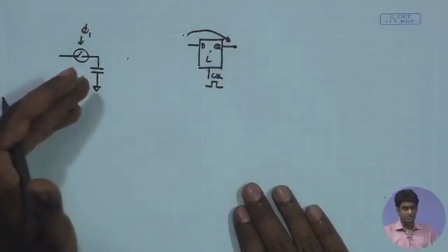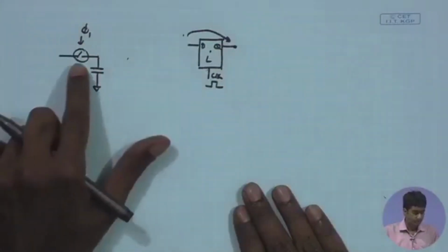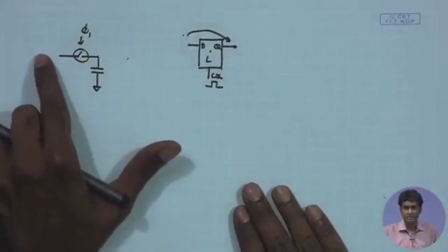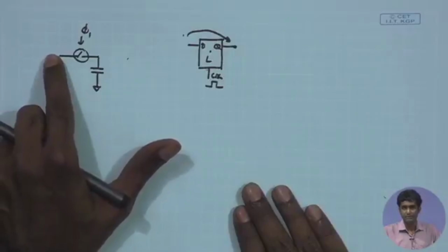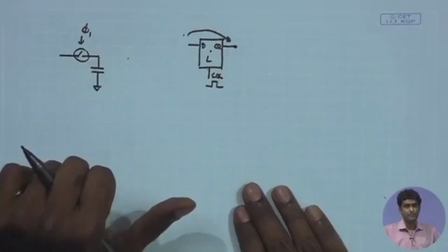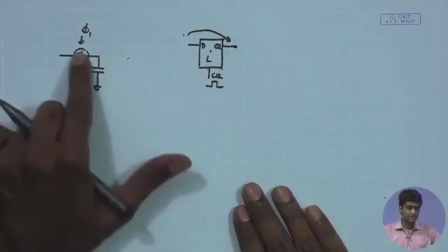In fact, we are having less concerns about the non-idealities of the switches like clock feed through, charge injection, leakage, etc., because here we are concerned with only two levels, VDD and ground, we are not really looking for a precise analog level, right. So, we can say that this is a very simple digital latch.